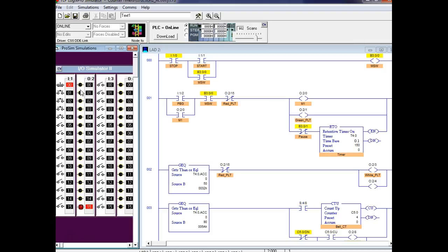Yeah, for Allen Bradley, the enable not only starts timing, it's also enable. So this one contact serves 2 functions for the Allen Bradley. You can see some of the timers, like on the Siemens, have an enable input. So not only do you tell it to enable, you have to enable it and do what? And also tell it to start timing. Of course, you can connect the inputs together.